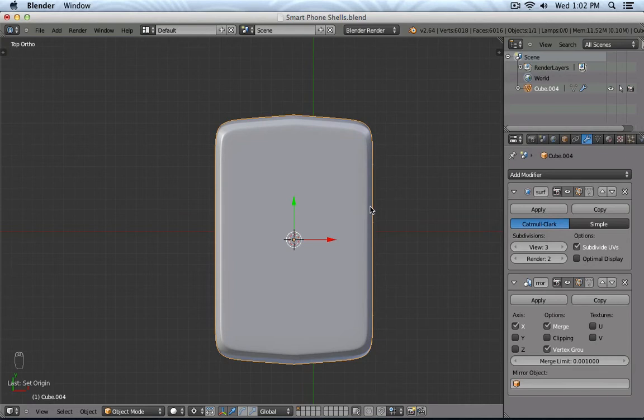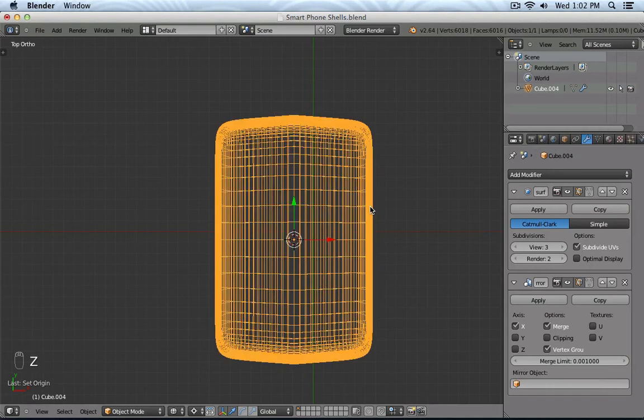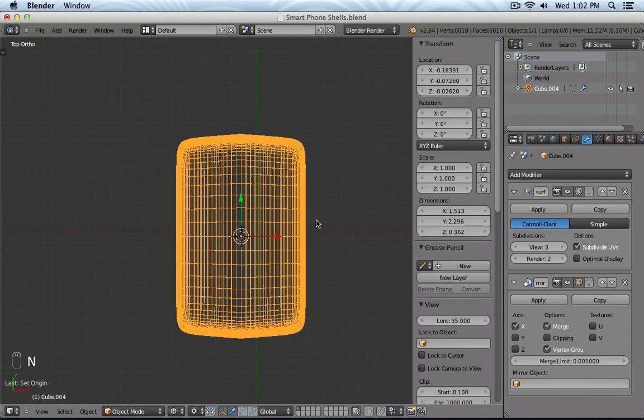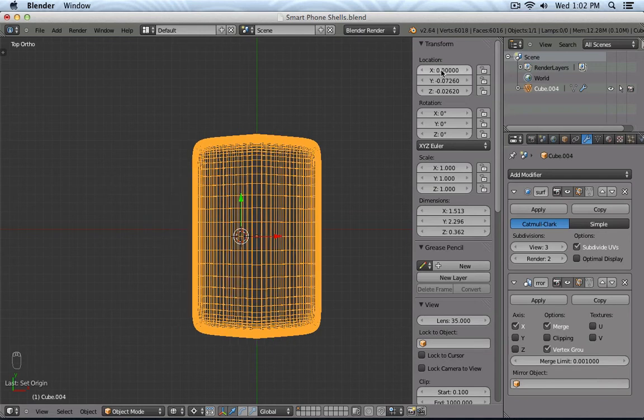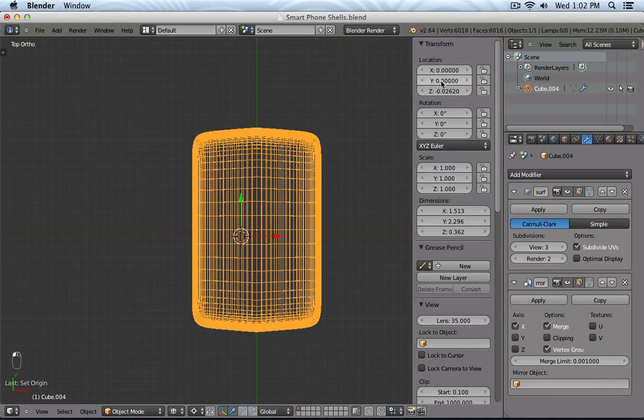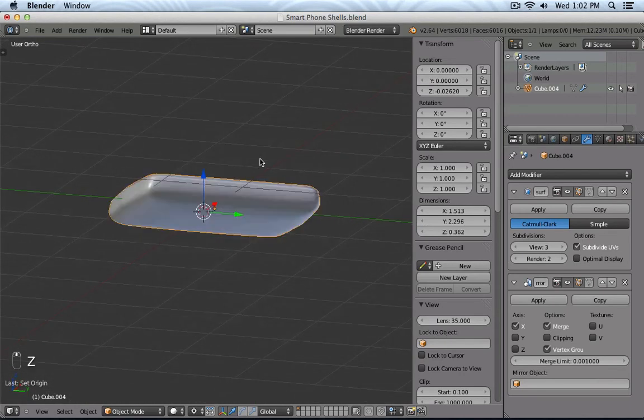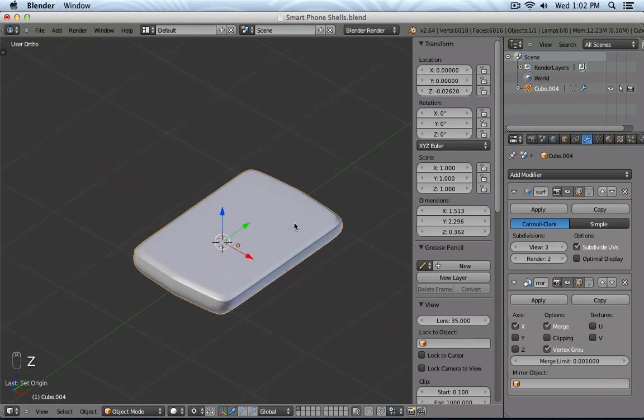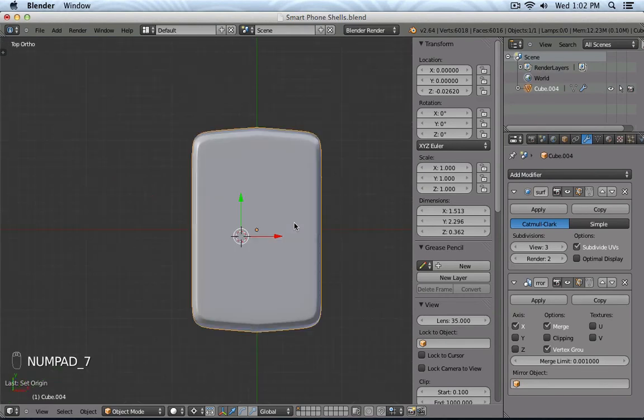and then you see that origin point was moved to where the cross section is, where my 3D cursor was positioned, and then this way my mirror effect perfectly lines up. Well, now my object is actually off the grid, so to reposition it correctly, I could press N to open the transform panel and into, for example, X and Y, I type in 0, and then my object is perfectly centered along the X and Y axis again.